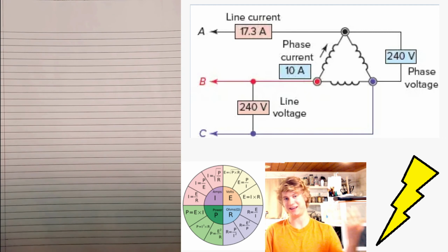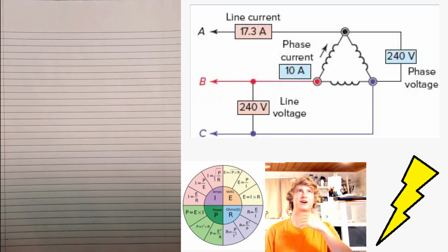And then it asked for the line and phase currents, so as we learned, those stay the same in a Y connection. Okay, next, how do the line and phase voltages and currents for a delta connection alternator compare in value? Okay, so we'll first think line and phase voltages. We just talked about this one in a delta connection. The voltages for line and phase remain the same.